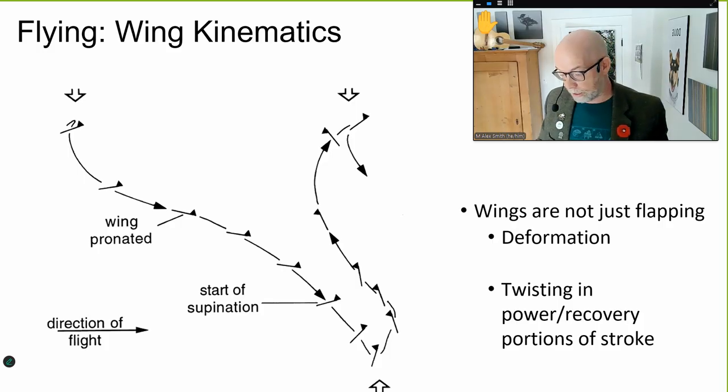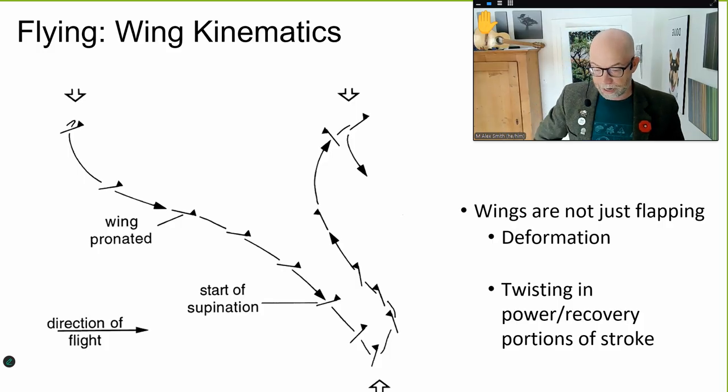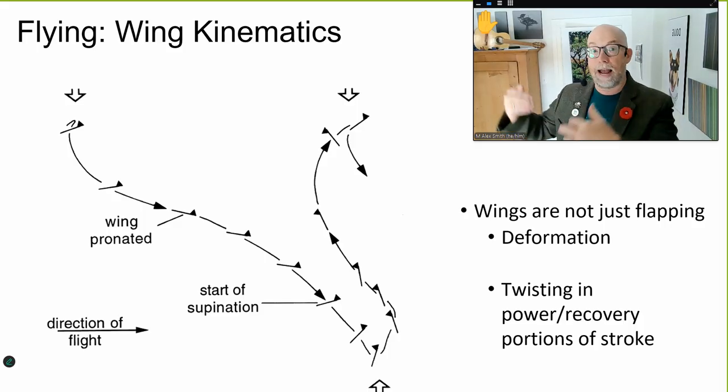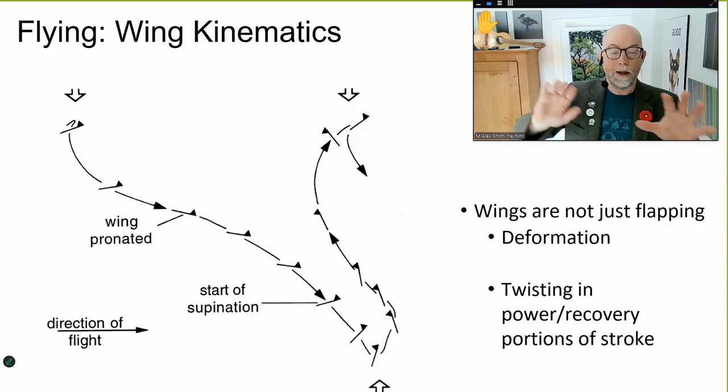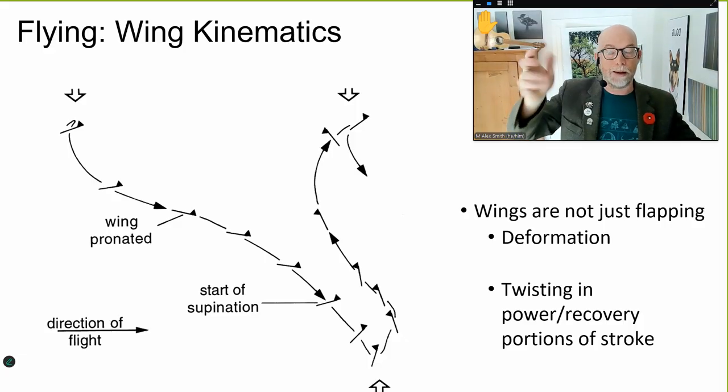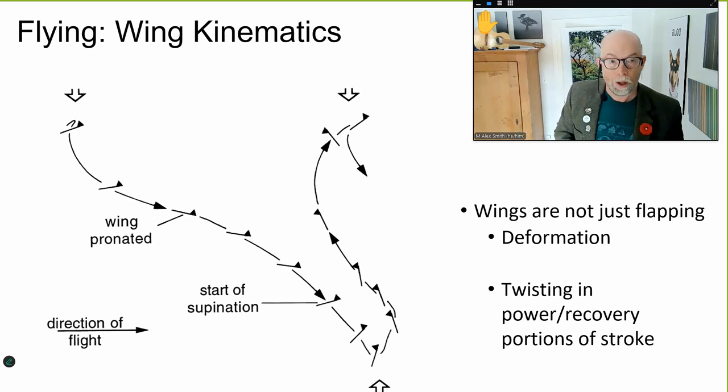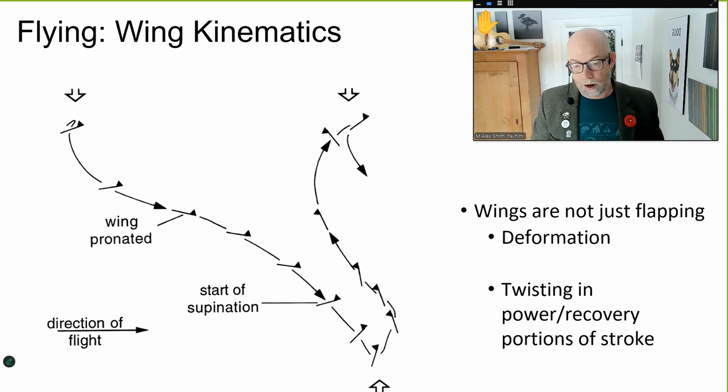So there's a twisting and a lot of deformation that happens in the wing. Now, when we think about the movement of these wings, either the flapping and the twisting that happens while the flapping has happened, because they're not disparate. As the flap happens, the twist is happening with the flap. We would measure that by hertz, and so we talk about wing beat frequency.